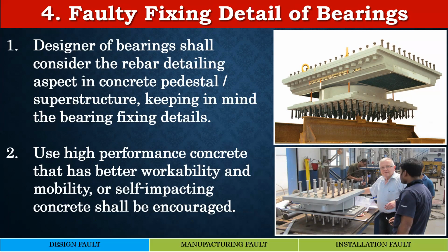to get into it. You can see an example of a typical bearing where so many studs are coming out, and these are to be embedded in the pedestal. Unless the reinforcement detailing in the pedestal takes into account the location and the direction of these studs, and unless that thought process has gone into the bearing designer's mind, you will never get a good solution.